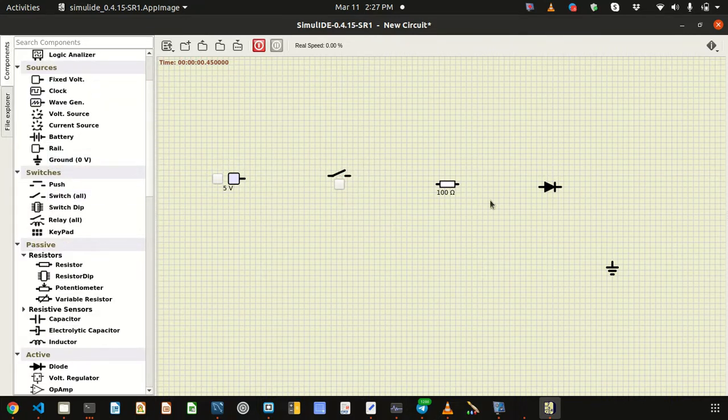All right, and let's connect the components together. To make the connection between the components, place your mouse cursor on one of the component's inputs or outputs, click it and drag it to the other component, and then click again, and there's a hard connection between the two components. And if I rearrange my components, the connections will not break. In fact, it will rearrange the connections as well.